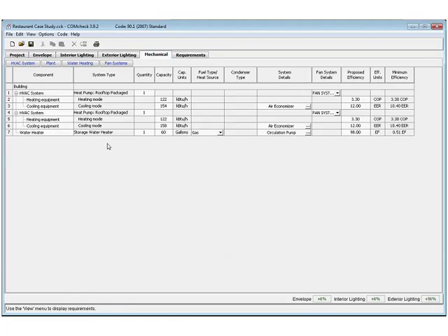Mechanical, they have two HVAC systems defined here. Rooftop package units, kind of similar in capacities, but the cooling is different, so they've separated them out, which is good. Air economizer came into play. I talked about that. So the system capacity here in the climate zone kicked in requirements of an economizer, and they had to define that system detail of what type of economizer it was. Show some fan system details have been defined. Well, let's go take a look at those in a minute. Efficiencies have been proposed and they have put in. Water heater has been entered.